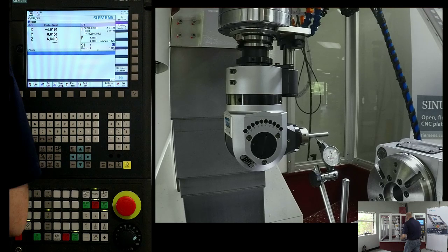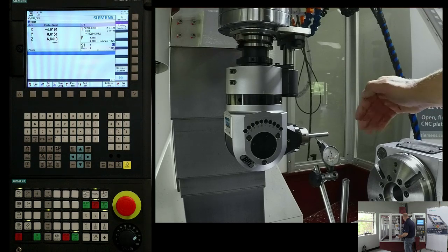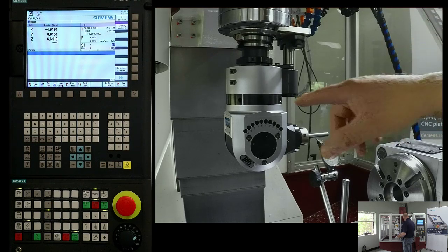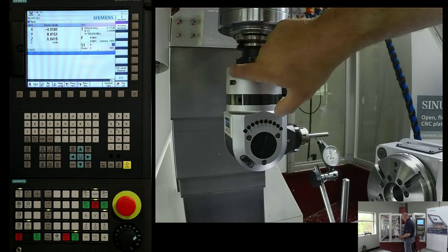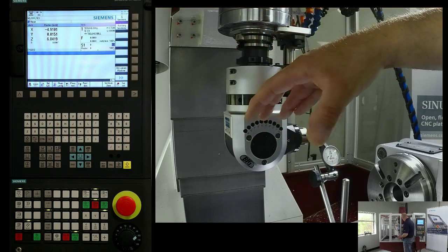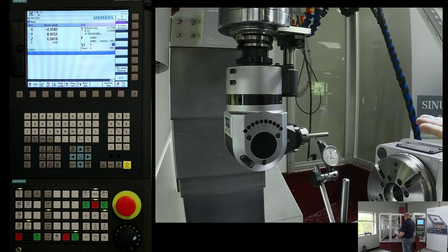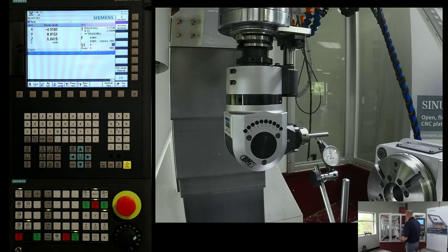Now, what I've previously done as well was I did the same process, but on the side of the bar, and I came across and I indicated to make sure the head was sitting basically parallel to the X. And if not, I can then adjust this head, this rotational head, by unscrewing these two bolts and basically tramming the head in until I got a 0 mark on the side and I'm 0 on the bottom. Once I've done all that, now it's time to find some geometries of this head.